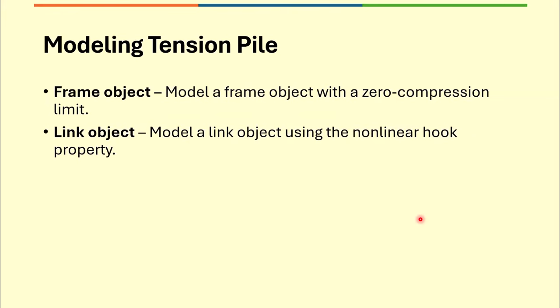In case you're modeling some tension piles, that can also be modeled using a frame object with zero compression limit or a link element using nonlinear hook property. This program gives you these options. But for both of these, we require nonlinear load cases.